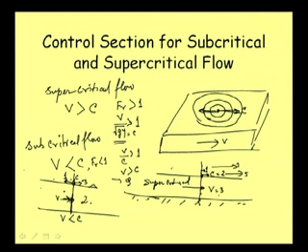This is what I have tried from my side to explain with some simple example and from the physical understanding of the situation, which really shows us why the control is at downstream for subcritical flow. If you do something on downstream, this is influencing the upstream. So if we want to compute subcritical gradually varied flow, then we should see what is there at the downstream point, that is, suppose the control section, we are getting that value, and that value is influencing the entire flow.